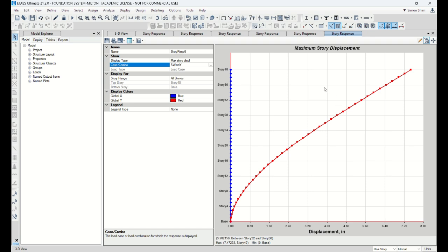All right, so up to here is the lateral load resisting system model. I show you. If you want to play around, change the wall thickness and concrete strength, do so. I think you have plenty of stiffness, so 24 inches might not be needed. So you maybe want to reduce the wall thickness and run that two, three times iteration and summarize your deflection under the service wind in X and Y. I think that will help you to understand better. So I think minimum two, three times. I think three times is perfect.